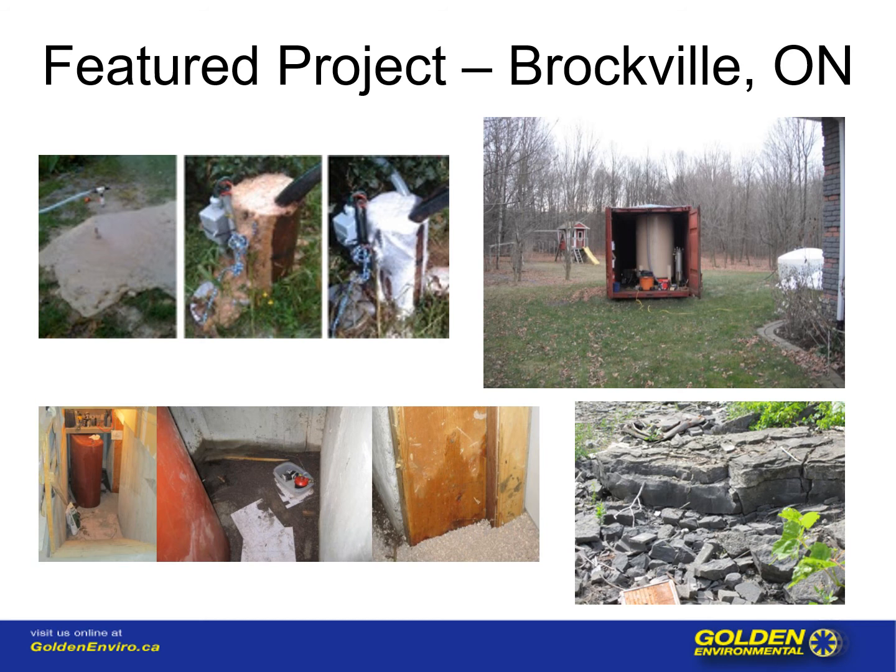Above that, where you see the top right, where you see that sea container, that is our mobile treatment unit with the activated carbon and necessary filters. It was discharged towards the left of that to the back. You can see where there's a tree house. That is where the clean effluent was discharged. To the right of that sea container, you see a recovery tank that we used. We pumped from their existing well into that tank, and that was our oil water separator. It was a very large oil water separator, but considering the volume of oil that we were pulling out of the well, it was necessary and very efficient.